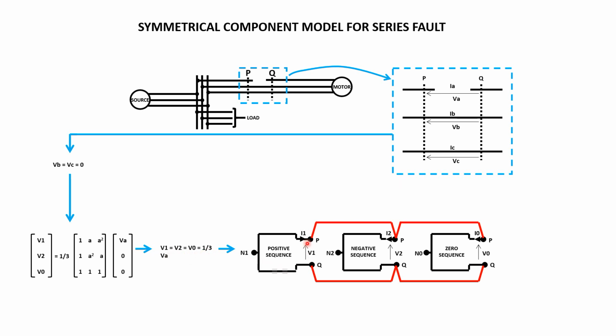That's how we nominate the series fault sequence models. All these voltages are equal to each other, which means the sequence networks are in parallel. Just remember the point N in the series fault is not connected to the other ports. It's not like a shunt type of analysis.